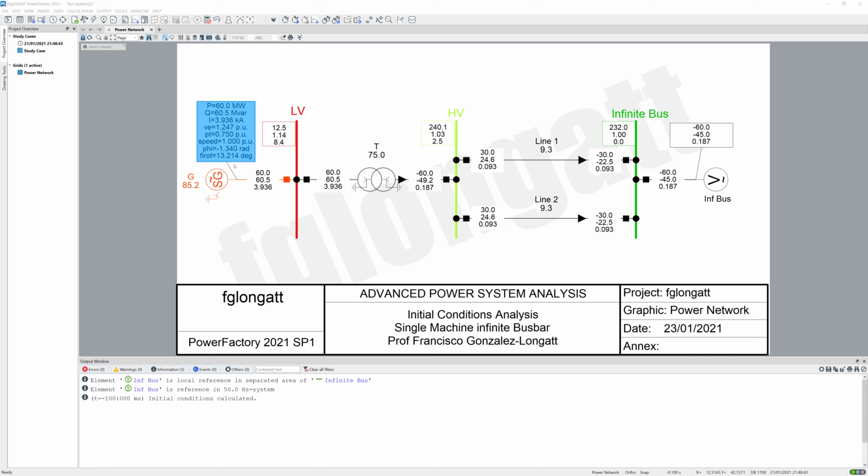There is no variation on the state variables, and from there we obtain a set of algebraic equations, and from there we can calculate the value of the state variables using the steady state assumption, okay? That is what the initial condition button does.